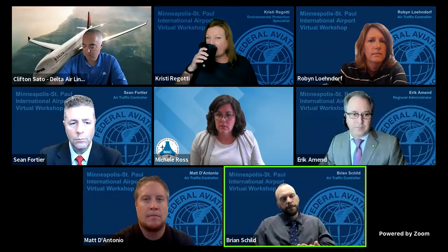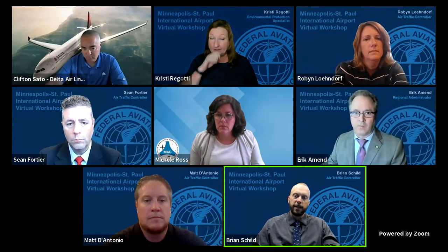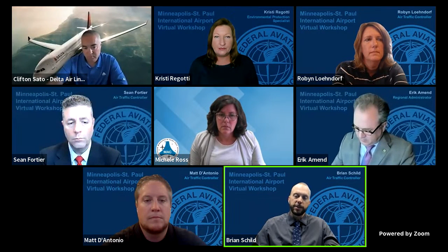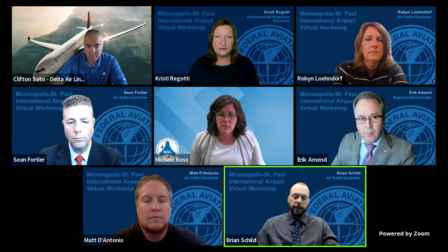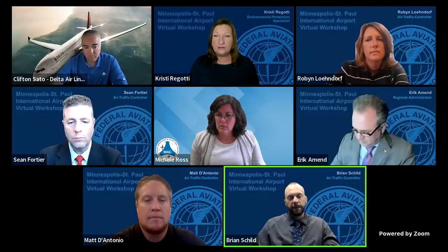Yeah, thanks, Eric. So I think the biggest change for us from the tower environment is going to be how we communicate that heading off of the departure end that I was just talking about. We're going to be able to give that information with the clearance, which is the thing that happens 30 minutes before the airplane starts moving. So the pilot's going to have that expectation of not just their big picture route of flight, but what we're going to do with them in the close-in environment to the airport. So they can plan for that.